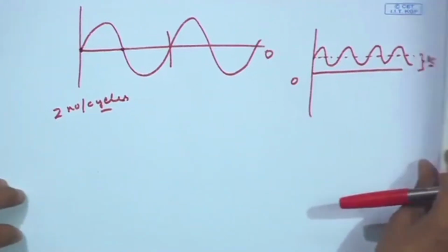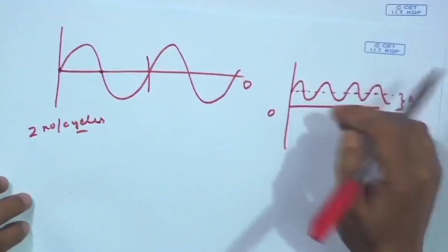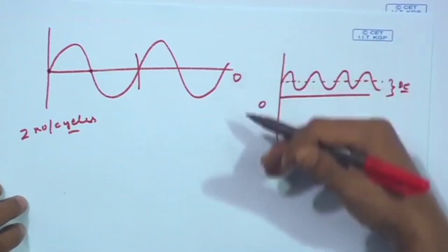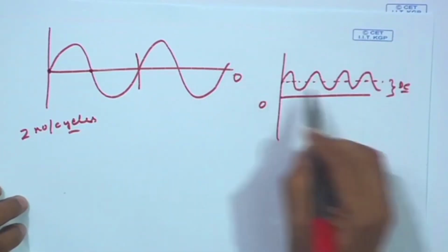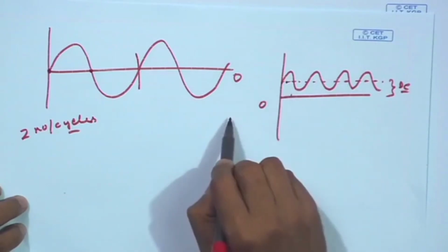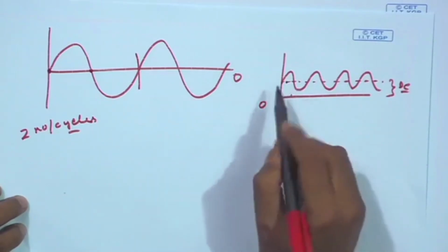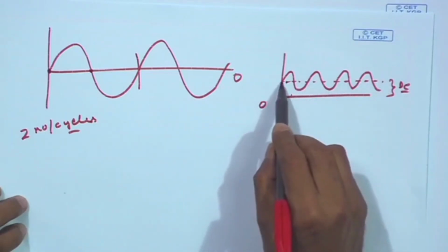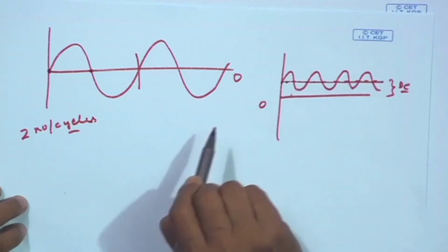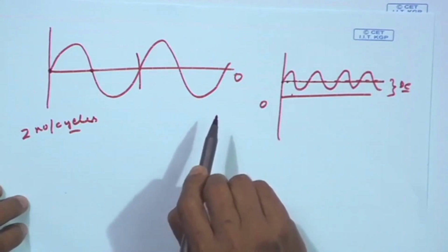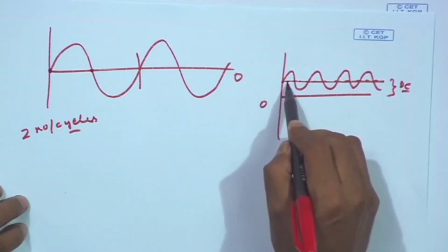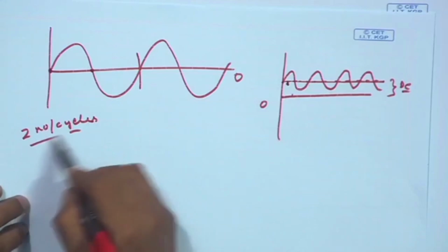There is a DC shift above during the recording, which is why the zero line is shifted to here. So, if it is DC shifted, I can either pass the signal through a low pass filter, or take the average and subtract it. So, first normalize the DC shift of the signal, then find the zero crossing.